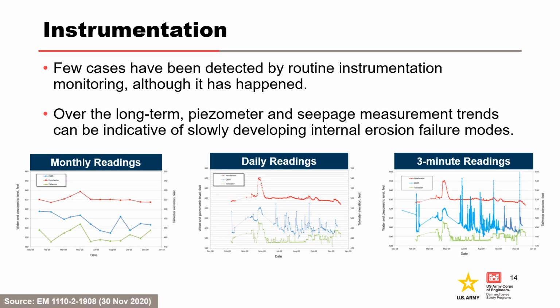Few cases have been detected by routine instrumentation monitoring, although it has happened. Over the long term, piezometer and seepage measurement trends can be indicative of slowly developing internal erosion failure modes. In addition to the location of the instrument, the frequency of instrumentation readings is an important consideration. Data resolution may be increased with more frequent readings if an instrument experiences highly variable conditions as shown in this series of plots. Monthly plots yield long-term trends, but correlations may be difficult to discern.